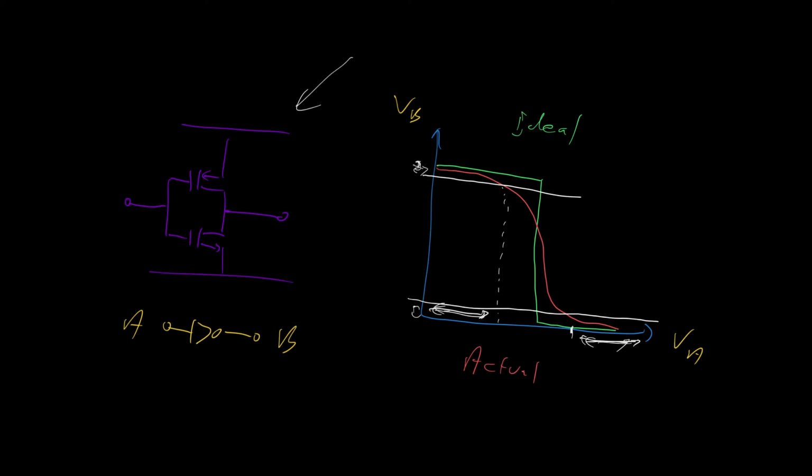It squashes the noise down into a very small region because the transfer function is very steep in the middle, very high gain if you like, and that gives us very flat, smooth sides here, which means large changes at the input produce only a very small change at the output. We get robustness to noise.